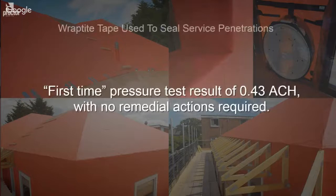So I'd explained earlier the 0.5 air changes per hour air leakage target. When they tested this project, it actually delivered a first time pressure test comfortably of 0.43 air changes per hour. So as I said, comfortably under where they'd set the initial target. More impressively, this air leakage result was achieved prior to installing our ProCheck 500 vapour control layer on the warm side of the insulation.